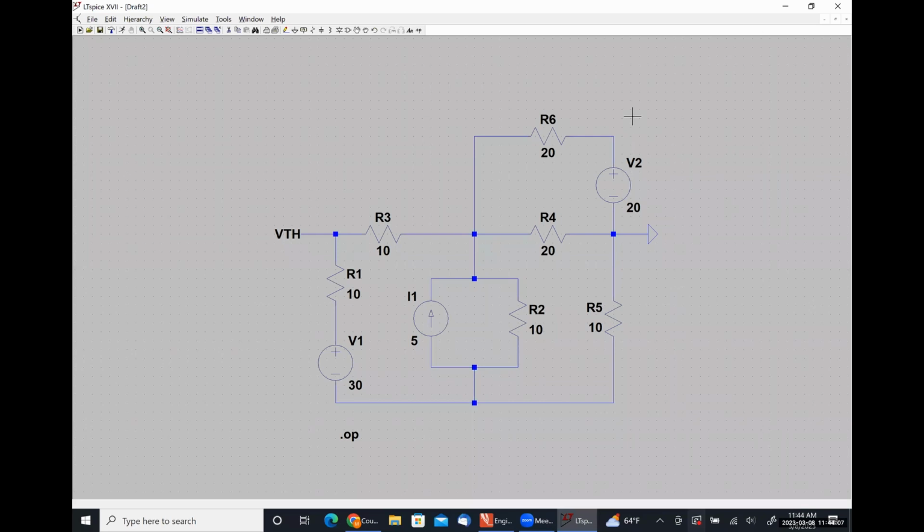Okay. So let's look at part B of this problem, right? Part B of this problem is finding the Norton current. So what do we need for Norton current? How do I find the Norton current? You guys have all had a class on this. So I need to short out my terminals A and B. Okay, so I'm going to do that with a wire. Does it remotely matter that ground is there at that node? Not at all. Okay.